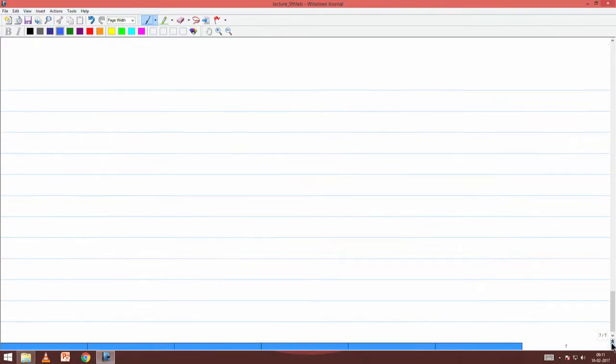Here we are actually solving the free vibration solution, and then we are led to believe that the free response, I should not use the word vibration, the free acoustic response, is only possible under the condition kL equals n pi. So, the associated frequencies will be called natural frequencies.